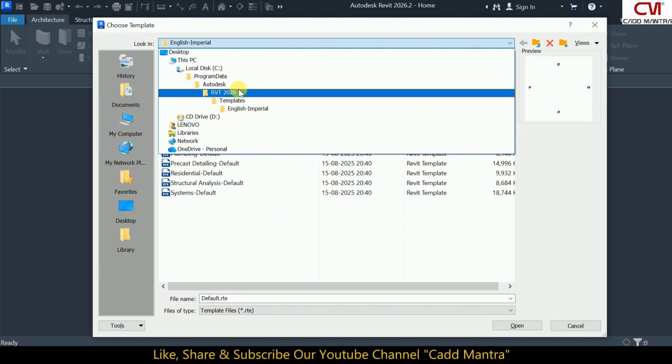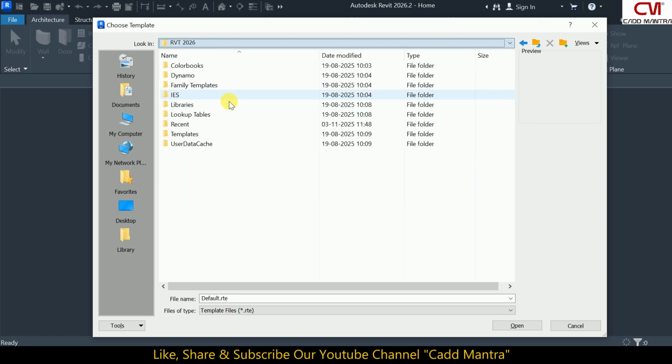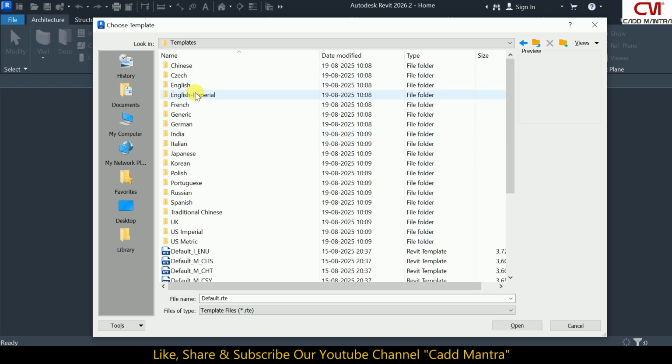So whichever version you have installed, you will find the folder named over here. In that we will want to go to templates, and then Revit 2026, and over here you can find all the libraries, templates, family templates, etc. that you will be using in the duration of the course. We will go to the templates, and we want the English template.